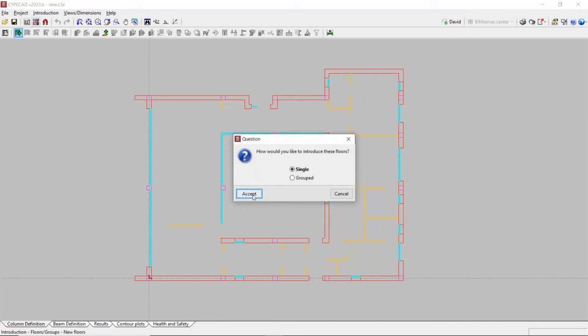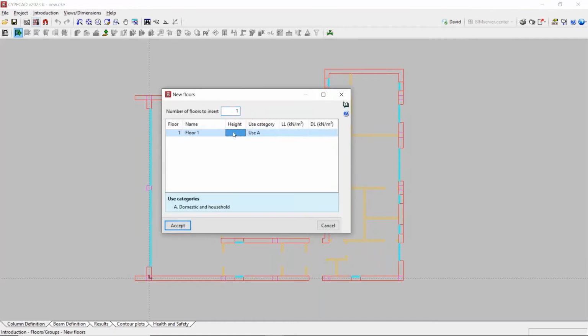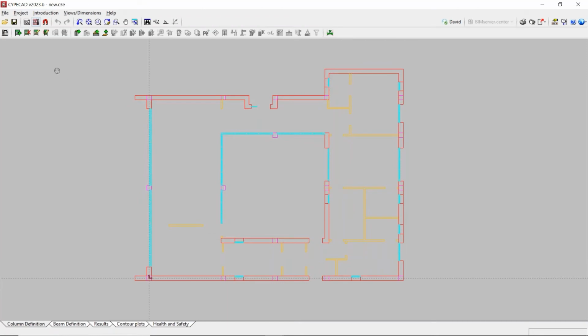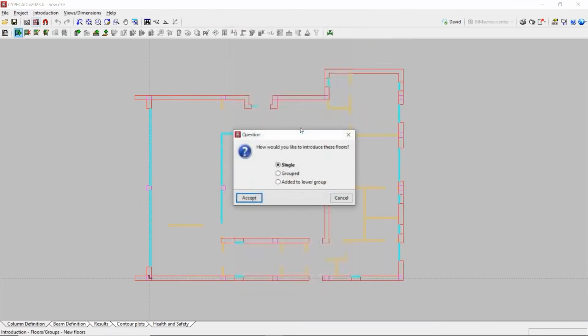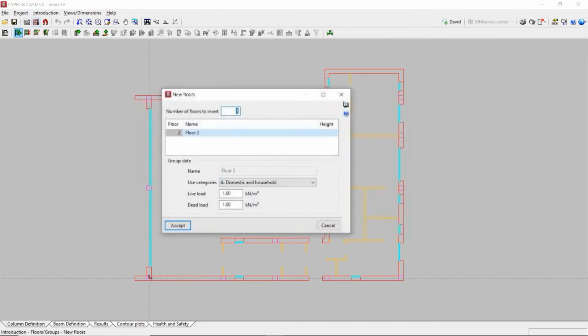Another thing that's important to mention is a lot of buildings are really similar vertically in that they have groups of floors that are basically the same. So one of the things this software does is it allows you to have different types of floors, and you only define them once, and then tell it how many floors there are of that type, which is really important.